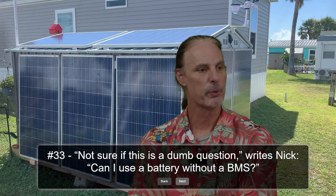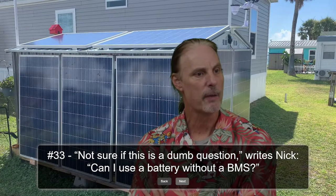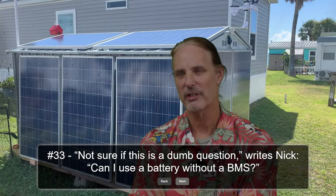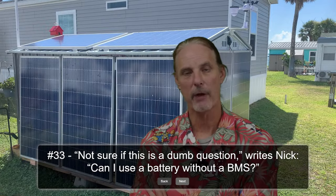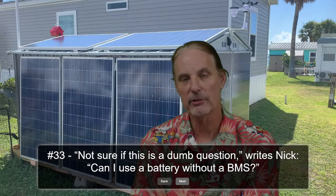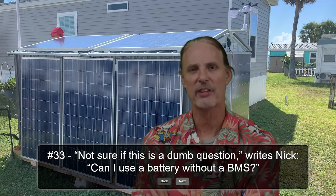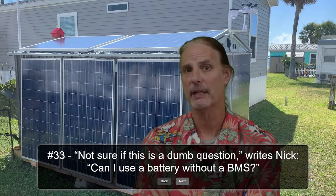Question number 33 is, not sure if this is a dumb question, writes Nick. Can I use a battery without a BMS? And I don't know if I covered this before. It sounds familiar, but no, you cannot use a battery without a BMS unless it's not a lithium iron phosphate. I would not connect lithium iron phosphate without a BMS. Can you? Sure, yes, you can. But it's a bad idea. The BMS is there to protect the battery, to protect your investment, to protect bad things from happening. Always.